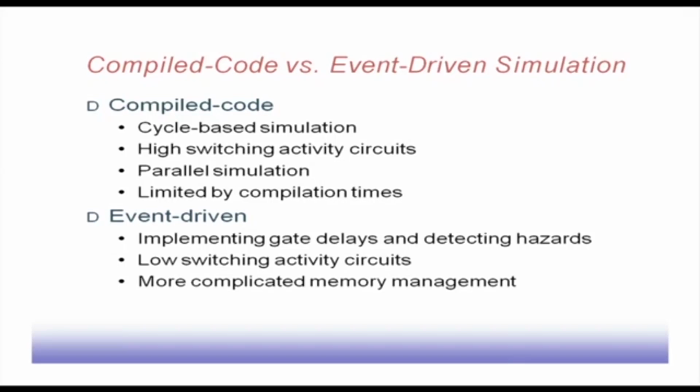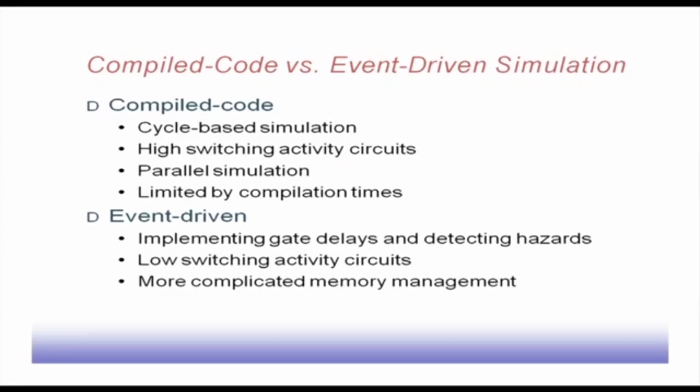The third important thing is that it is code-based simulation, and we have seen that it can do parallel simulation. Multiple tests, multiple stimuli can be simulated in parallel, because it takes help of the word size of the processor. That way it can help us in running the simulation faster. However, compilation times are necessary, so naturally it will be limited by the compilation time. We have to give extra time for doing compilation, and for anything you change in your circuit design.